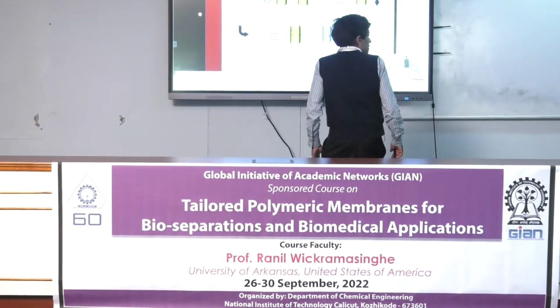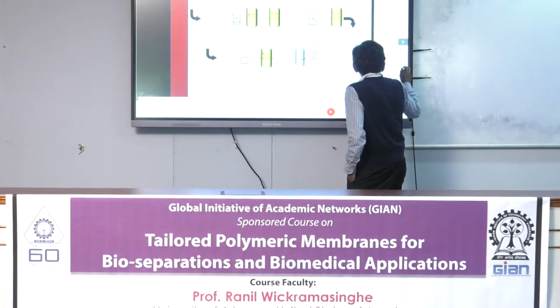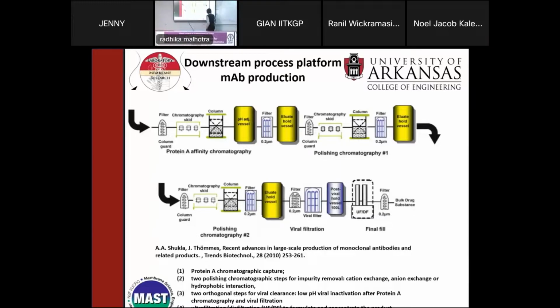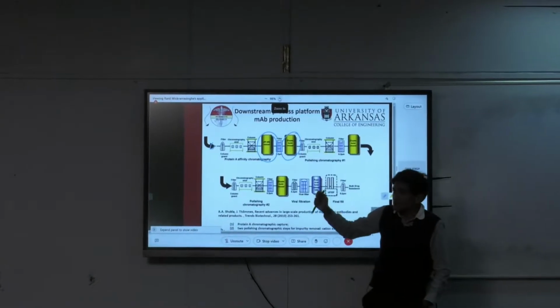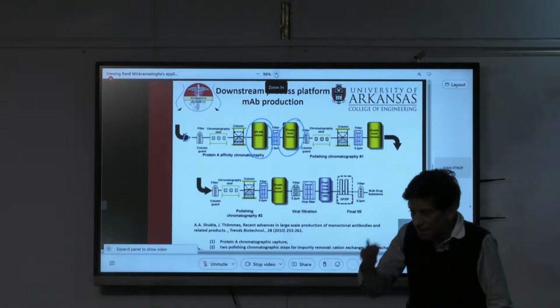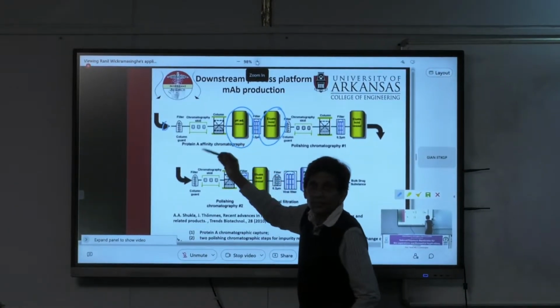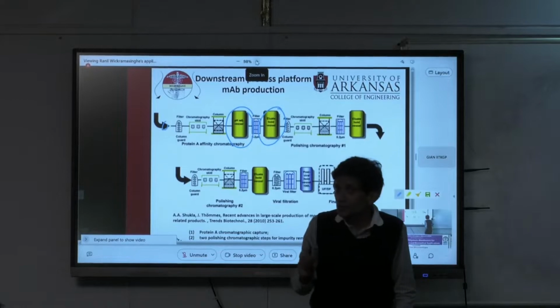So that's one aim, that's here, okay? But in existing work, currently, there is definitely a virus clearance step here, pH adjustment vessel, elute hold vessel. So typically, you elute from the capture step, okay? So this is a bind elute chromatography or adsorption. You bind, you elute your product of interest, and then you adjust the pH. So there is virus clearance, but that's by inactivation, not removal.